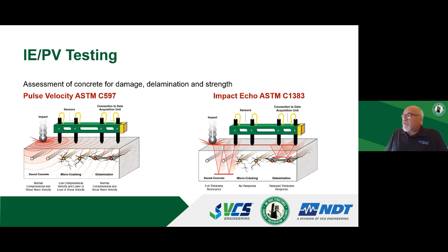Now, we're following two existing ASTM procedures. Pulse velocity, remember that's the surface wave. That's in the concrete side of the spec, C597. And impact echo is also in the concrete side of ASTM, and that's C1383.